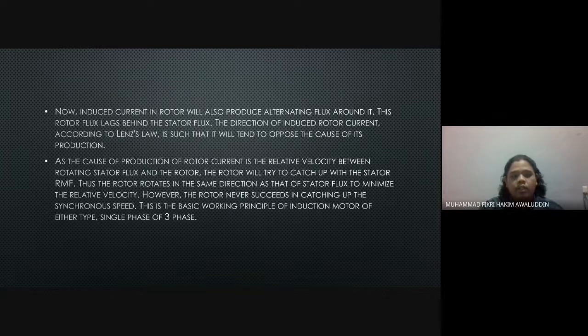Thus, the rotor rotates in the same direction as the stator flux to minimize the relative velocity. However, the rotor never succeeds in catching up to the synchronous speed. This is the basic working principle of an induction motor, of an ideal type, single phase or three-phase.